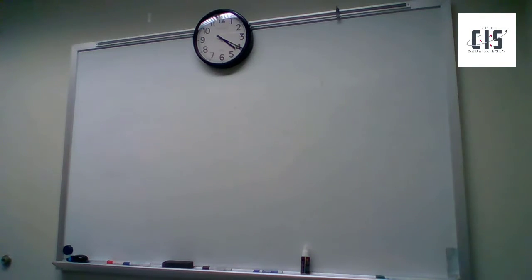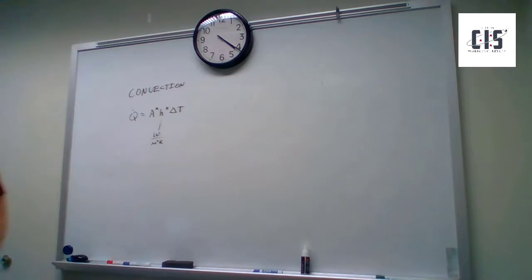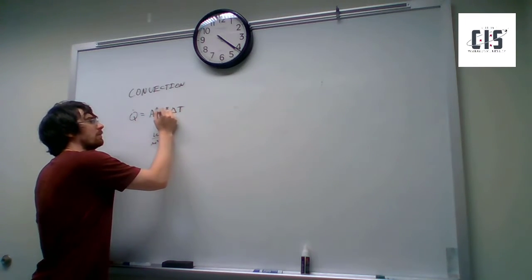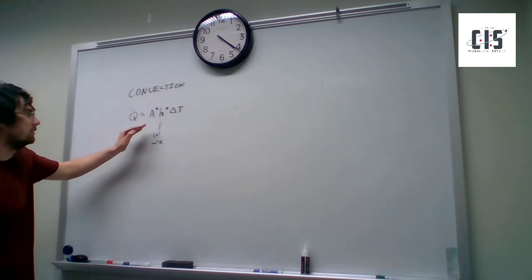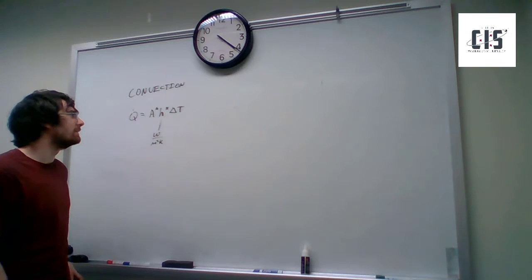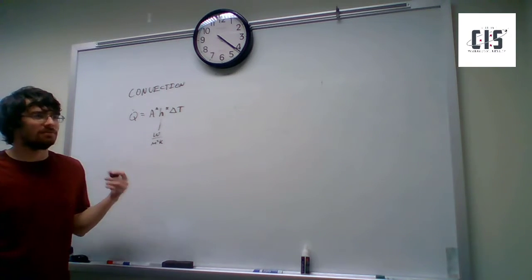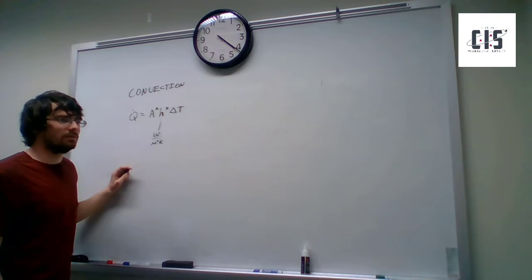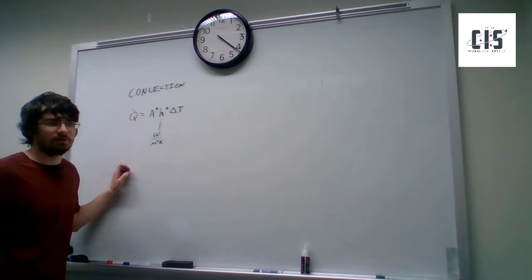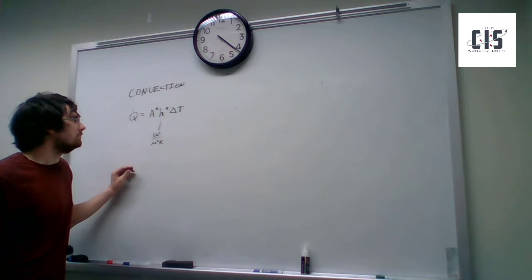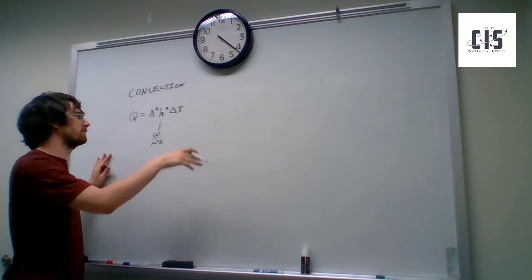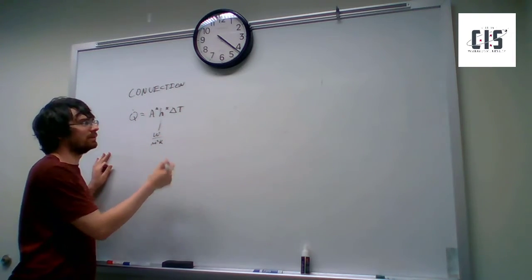Sure. Yes. Okay. So we have a heat transfer coefficient, and you may ask, well, what does that depend on? It depends on a lot of things, and we're not going to go into it. It depends on whether the convection is forced or natural. It depends considerably more on the temperature of the gas than it does for conduction. It's going to depend on the surface and what the friction is on the surface, and a whole bunch of other things. It's a mess, but I'll give it to you anyways.